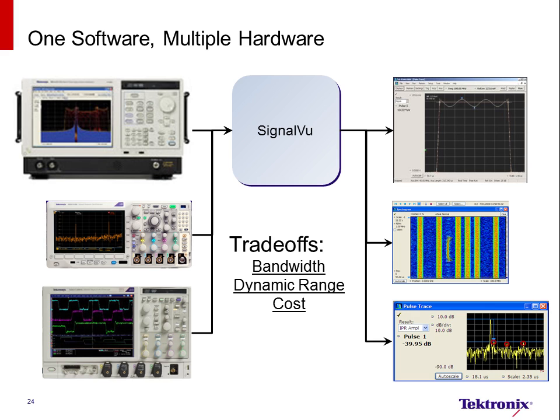Performance oscilloscopes have SignalView options, which add radar and many more measurements to the oscilloscope, all with the same user interface. Multi-domain oscilloscopes can be used with SignalView PC, using the MDO to acquire data and automatically pass it to the software, which runs on a PC. The MDO is not only a lower cost solution, but also adds more triggering options to the measurement system. Logic triggering on the MDO, for example, can synchronize logic events with RF waveform captures.